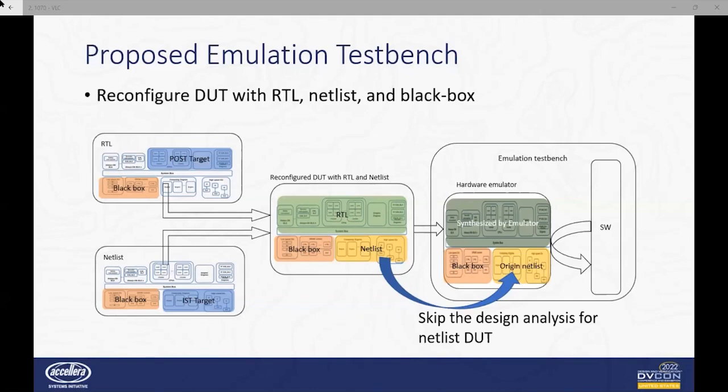With the help of this test bench, we can verify the full pattern list for both memory and logic. It enables us to create and run real usage scenarios as well. When we create and run usage scenarios, we got a lot of debugging help from emulator technology.